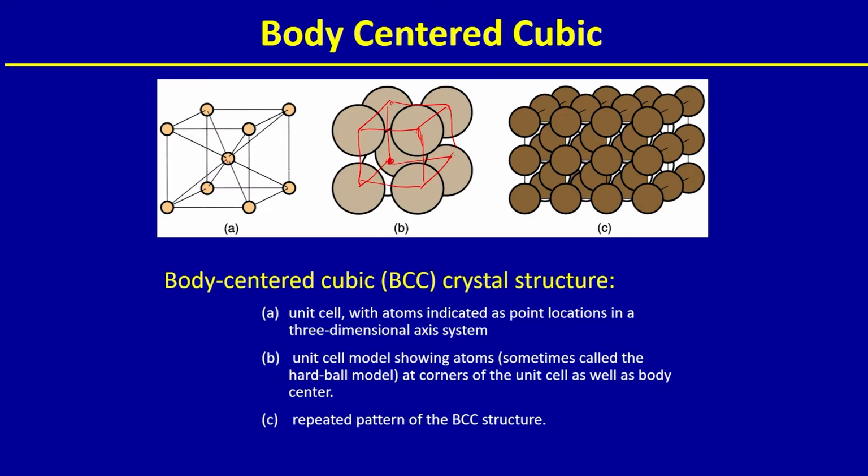So, this atom which is at the center, you can clearly see this one, remember this. Hence you can generate this structure in 3D in all x, y, z directions, put it together in a repeated pattern and generate it. The unit cell will have 1 atom at the body center and 1 atom at each corner of the cube. So, virtually speaking, it has 2 atoms, because each of these corners is shared.